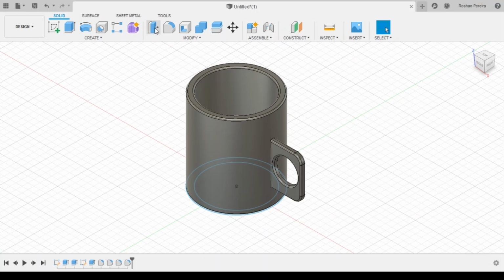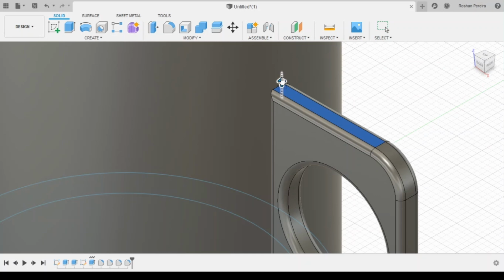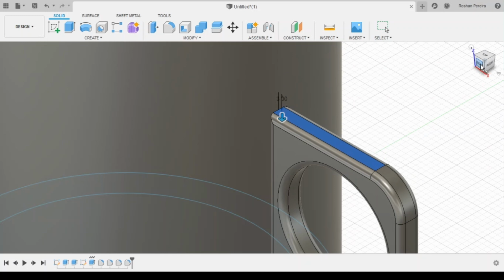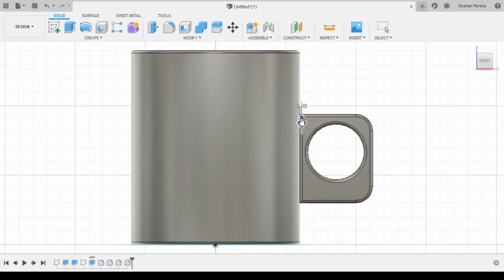It's the same thing. You click on press pull and then you select the section that you want to select. It can be used for extrusion. So see, when I pull it up or pull it down, I can change the height of it. I can change the extrusion in that direction. So if I go on the front plane and I make a fit, and here I change the height, so I can make that -3.